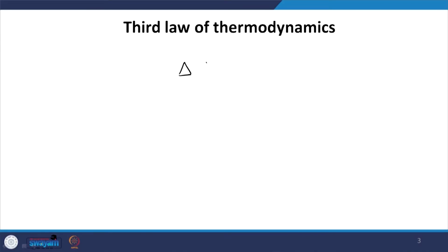However, we make a small detail to the argument there. Now I can define the delta S of whether the system or a surrounding, but we are more concerned about the system in general. So, delta S can be written as the integration over dq reversible by T, where T is my temperature, and the integration is done over the initial and the final states.